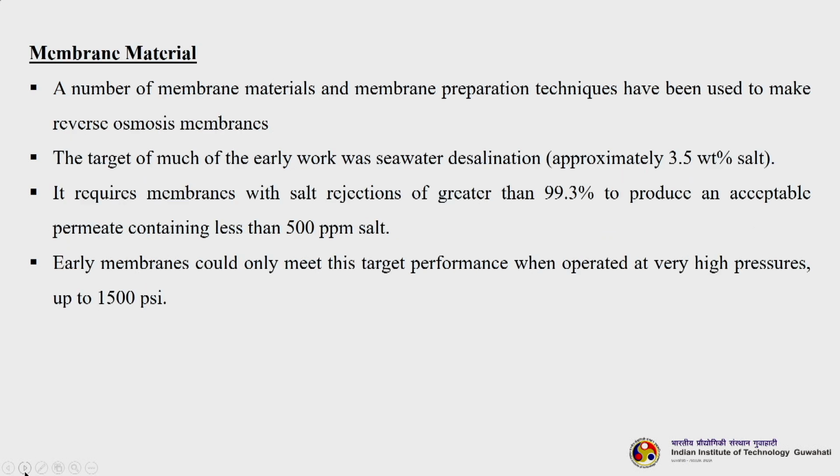Now let us talk about the membrane materials for RO. A number of membrane materials and membrane preparation techniques have been used to make RO membranes. The target of much of the early work was seawater desalination, about 3.5 weight percent of salt. So, RO was primarily developed for desalination purposes, though RO is being used for other applications also.